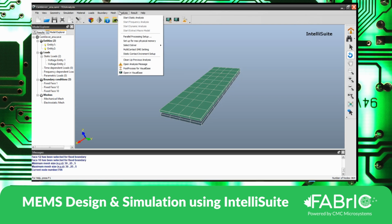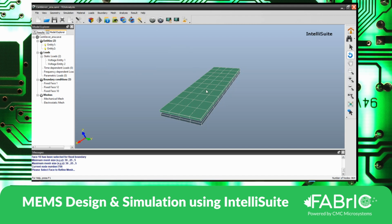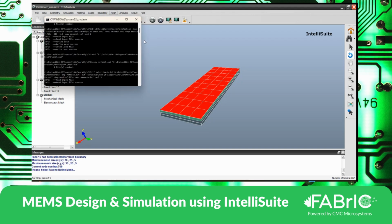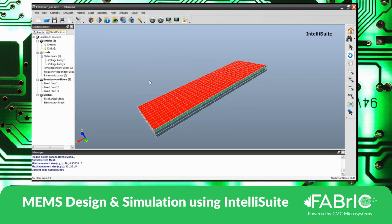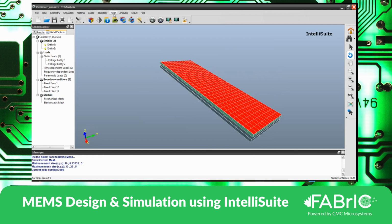So now I would suggest go to mechanical mesh, modify, pick on geometry, and then I would say only this geometry. I want to reduce the element size to 10 micrometers. Then I go to update mechanical mesh and then click update mechanical mesh. Only the one which has the deformation capacity is meshed effectively. Okay, so this will help.